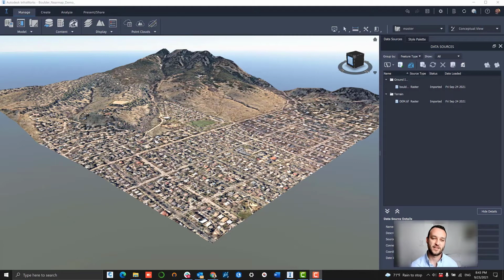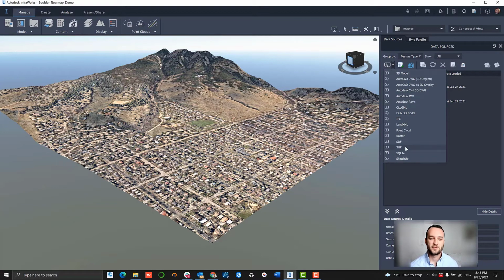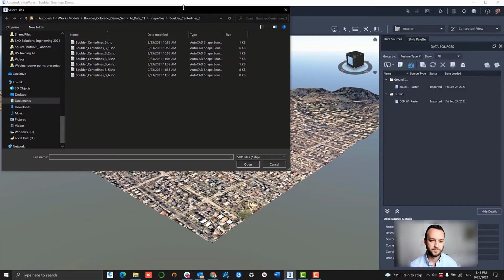And we're going to demonstrate that here today in the InfraWorks environment. So the first object that I'm going to use is our roads layer, right? So we recognize this as asphalt and concrete. What I've done is I've done a little bit of post-processing. So our algorithm identifies edge of pavement, but I've gone ahead and done a little bit of scripting to identify the road center lines. And then we're going to digitize those by creating road layers in InfraWorks.